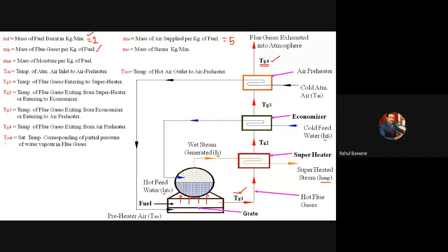So suppose we have generated steam, and it has some moisture. After steam is generated, if we supply heat, steam will not start directly increasing its temperature. Its quality increases. That means suppose initially it has 30% moisture. If we supply heat to the steam, its moisture gets reduced, vaporized. So after heating, we find that 20% moisture is there. Again supply heat, 10% moisture, then 5% moisture.